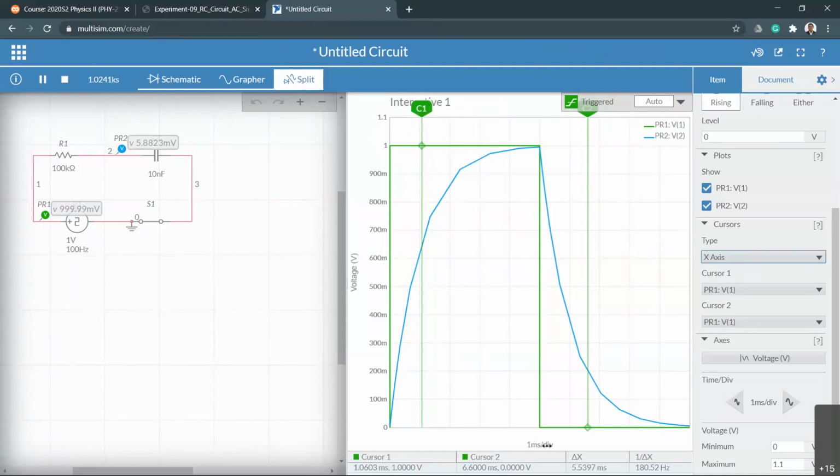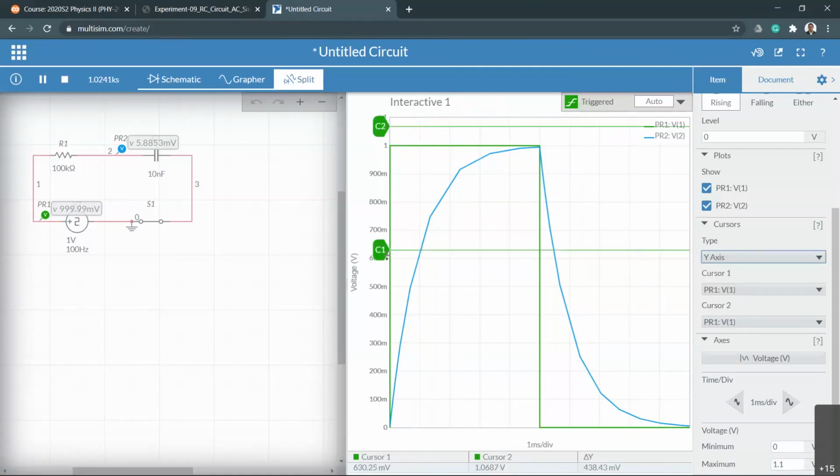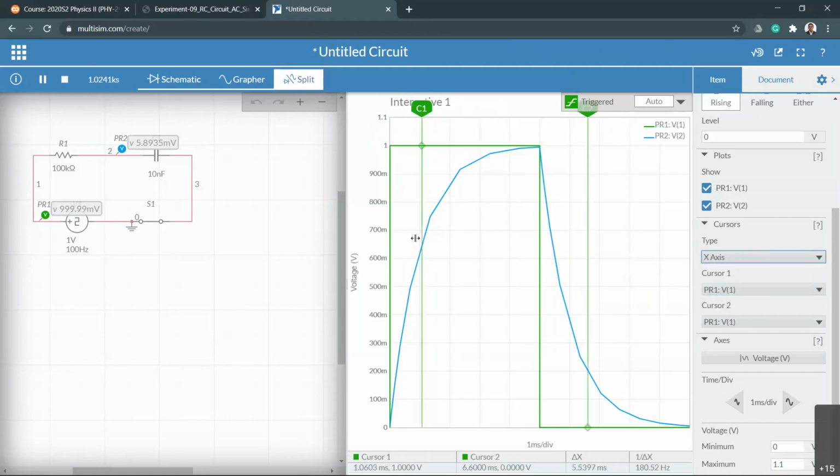Good. So you can measure that two ways. One is actually putting the cursor directly into y-axis and then finding the 63 percentage. That's a 630 point, right? Then you have to mark that. There's no way to mark this. Okay, you have to really eyeball it and then basically remember where that crossing point is. Then change the cursor into x-axis and take a look whether that crossing point is the previous crossing point. Then read this number directly.